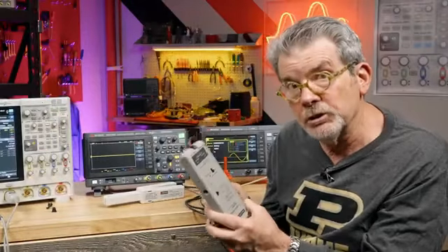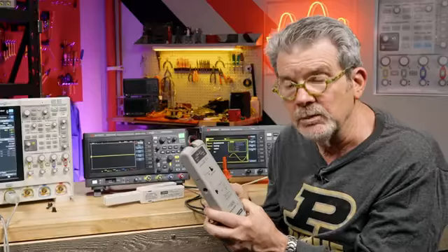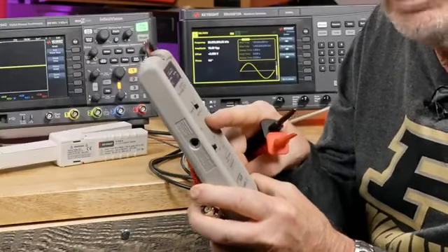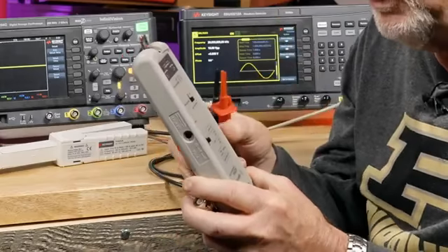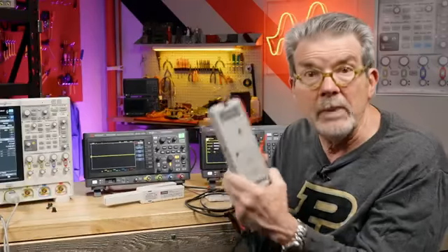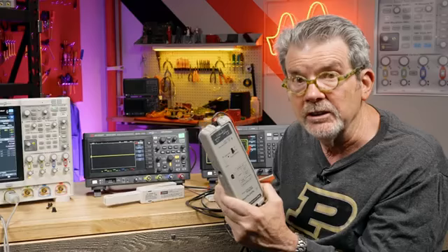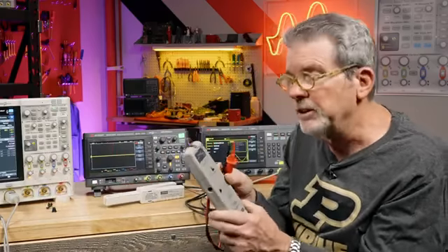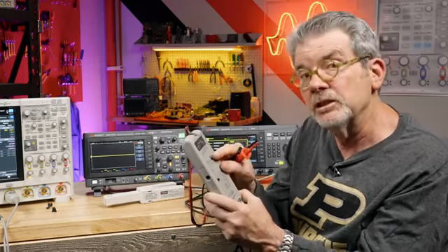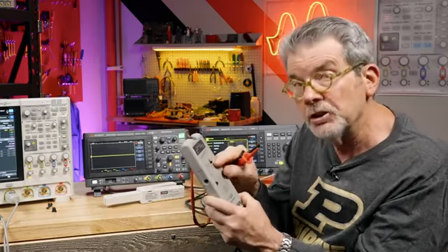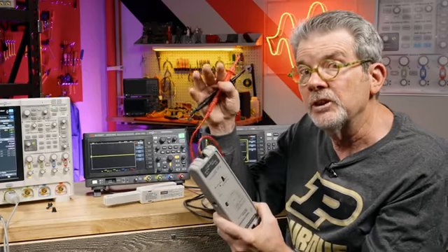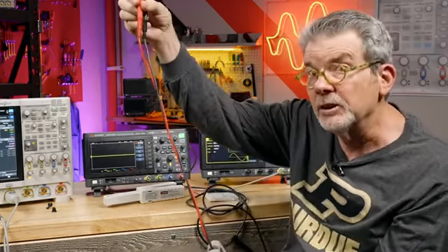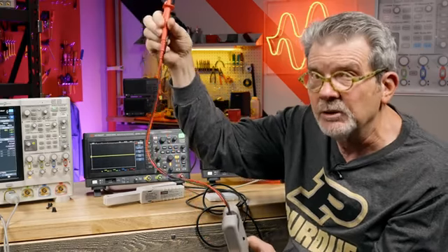This is a high voltage differential active probe. So it also has an amplifier in it, and it requires power. This particular probe gets power from a battery that's installed inside here. So it doesn't pick up power like the high frequency probe over here. Now, this one has a 10-to-1 setting and a 100-to-1 setting, so we can measure very high voltages. Now, notice this one does have very long leads, very different than the high frequency probe.